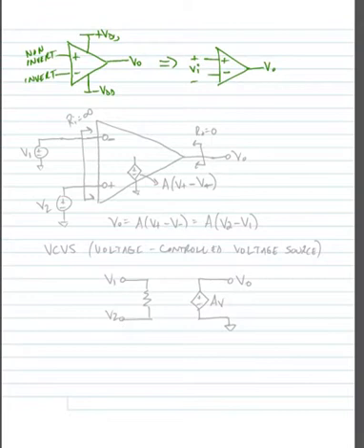Knowing that our operational amplifier has a limited supply voltage range. So looking at our operational amplifier equivalent circuit, we might see a symbol where we have an input terminal, our inverting terminal, another input terminal, our non-inverting terminal, and we show this with a broken connection to represent that we want a very high or infinite input impedance.